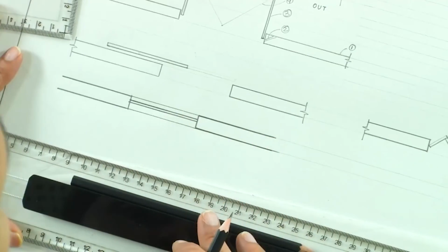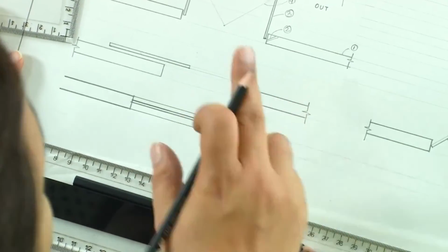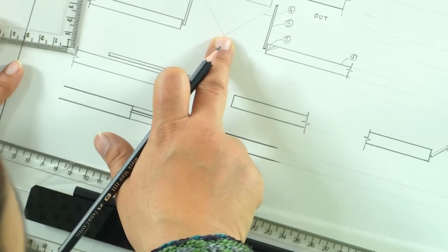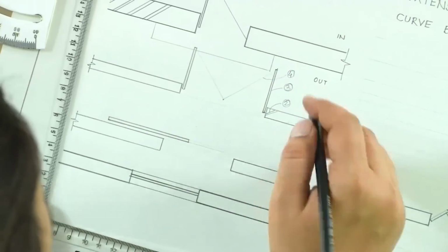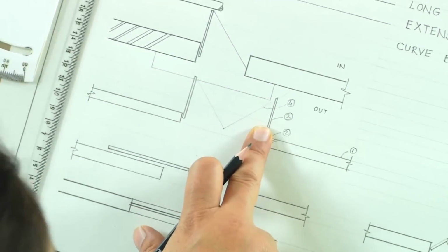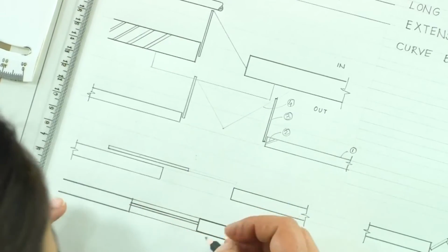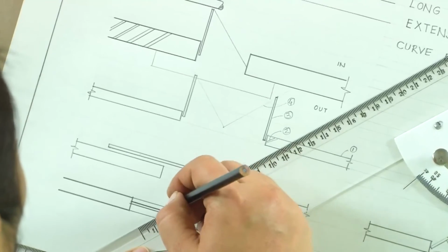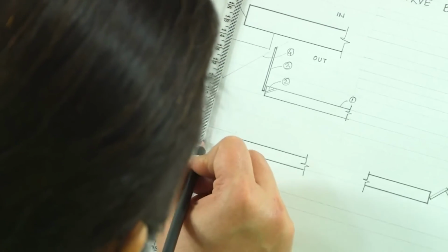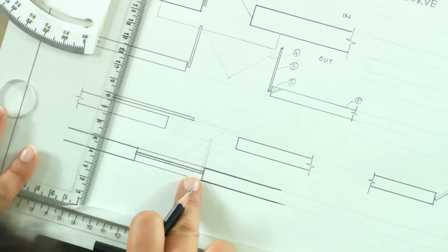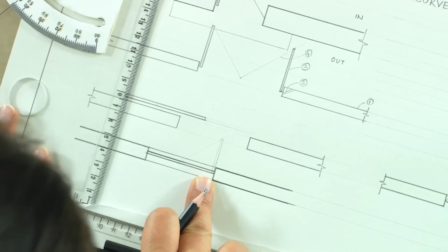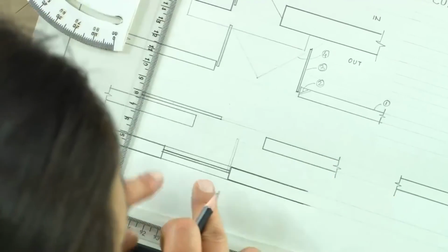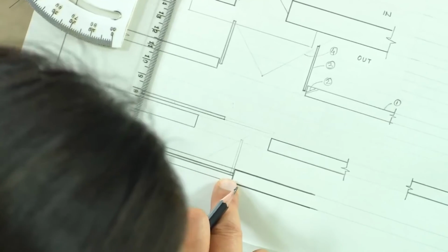Now, if you have an openable window, you will draw doors or the panels like the one which we have seen in door. So, we will have a representation for an openable window. So, thin line and a window pane. So, this is how we will draw the window with an openable pane. Suppose we have a fixed window, we can just draw it like this.